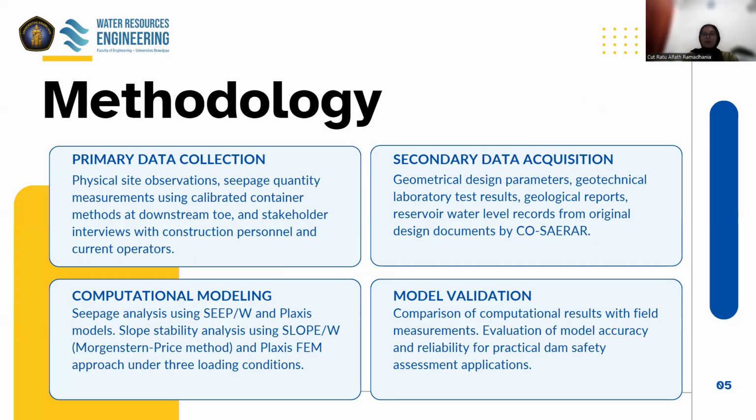The second step is the secondary data acquisition. The secondary data are the geometrical design parameters, the geotechnical laboratory test results, the geological reports, and the reservoir water level records from original design documents.